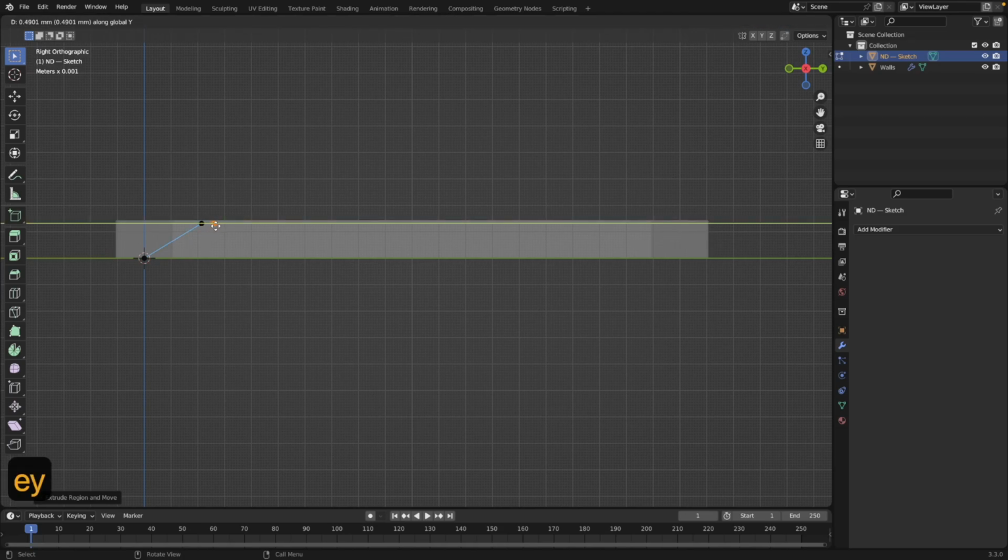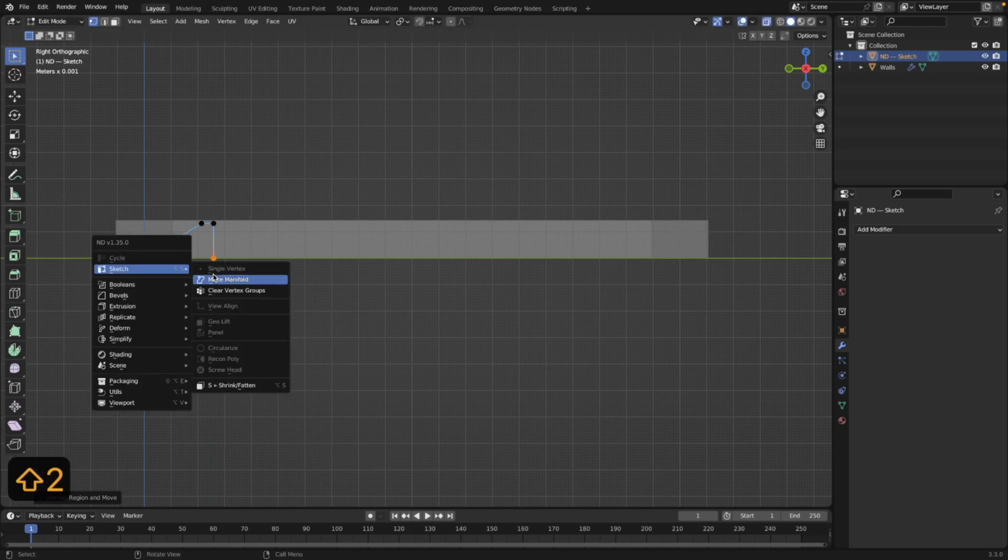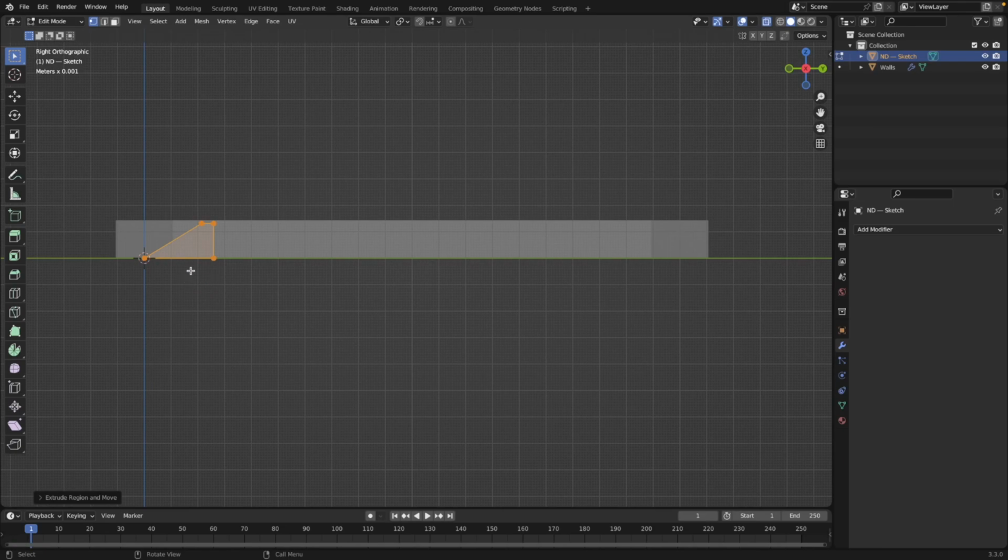So I'm gonna go this way just to give it a little bit of a horizontal flatness along the top edge, so it's not a sharp point that it's going to. So something like this. And then we're gonna extrude it again down along the Z axis, straight down. So we're gonna do something like this and go all the way back down to the 0 point here. Something like that. And then we'll use the ND menu and choose Make Manifold to fill that in.